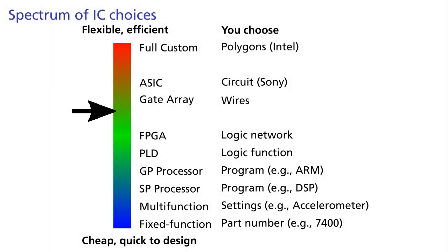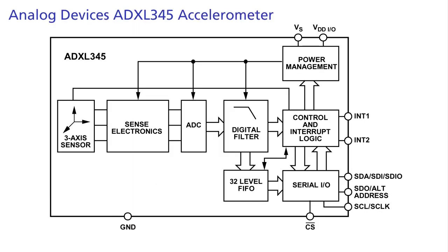The ASICs and FPGAs from the previous lecture were specified as digital logic circuits, a net list of gates and flip-flops driven by a clock. By contrast, the processors we have been talking about, including general and special purpose, are fundamentally stored program computers in that their behavior is customized by giving them a sequence of instructions to execute. A third group of chips perform computation and are configured through software, but do not accept programs. Instead, these chips are controlled through command and status registers, something like buttons and lights that can be set and read from software.